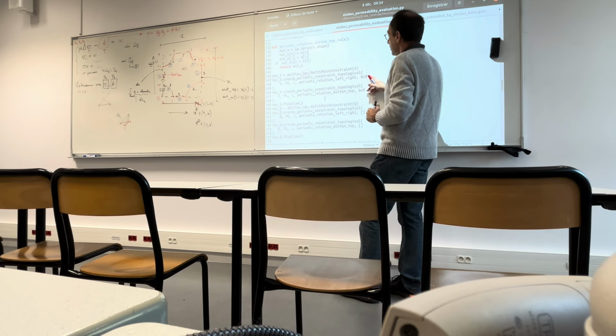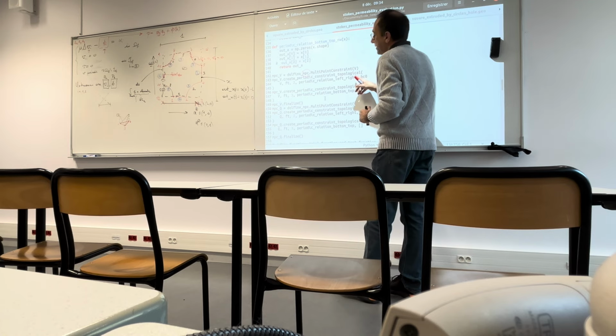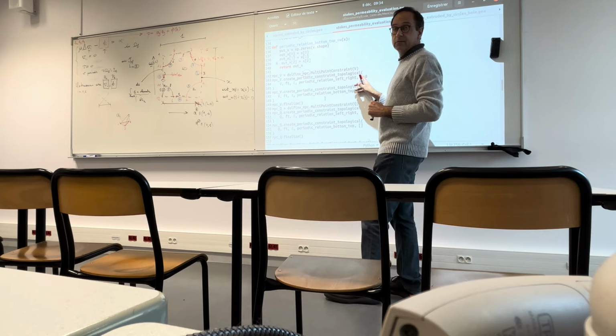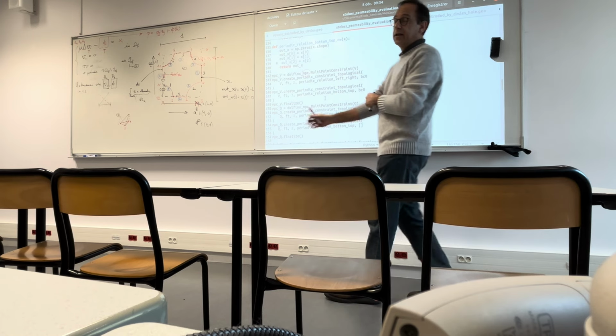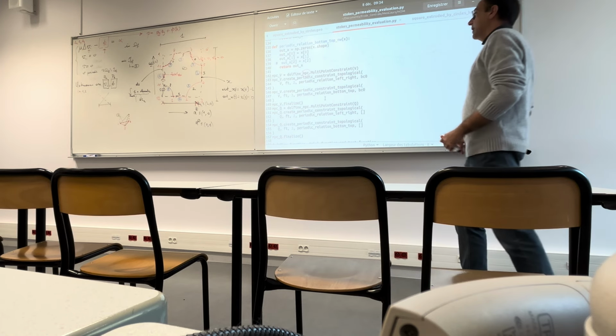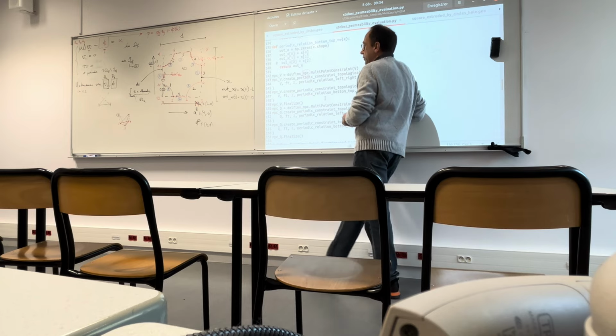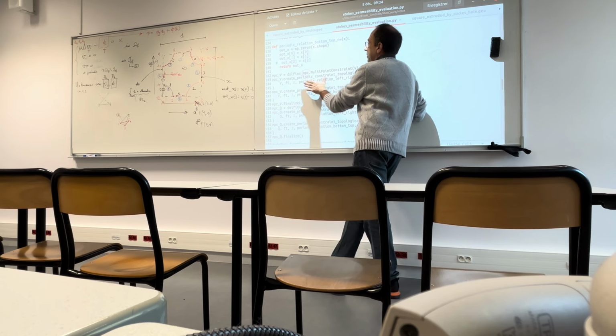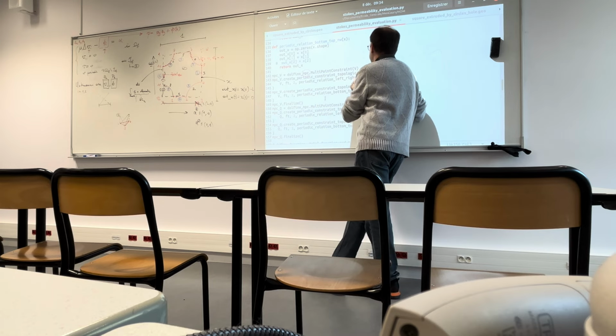And I also specify what are the other boundary conditions given for velocity. So this is just the way in which the subroutine has been created. It doesn't want only periodic boundary condition, but it wants essentially to know what is the full set of boundary conditions for, in this case, the velocity.